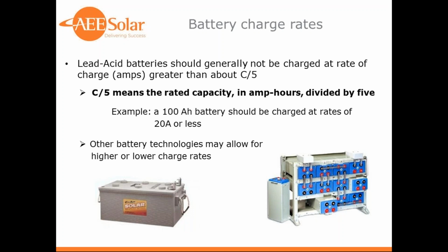Some manufacturers allow harder charging. Certainly other battery technologies might allow for harder charging. But at this point, lead-acid batteries are still pretty much the standard in these kind of systems. I think we're going to see more advanced battery designs in the next few years that may be highly competitive. Right now, they're a lot more expensive. They're not well integrated into the off-grid equipment yet. So we're still pretty much standardized on lead-acid batteries at this point.